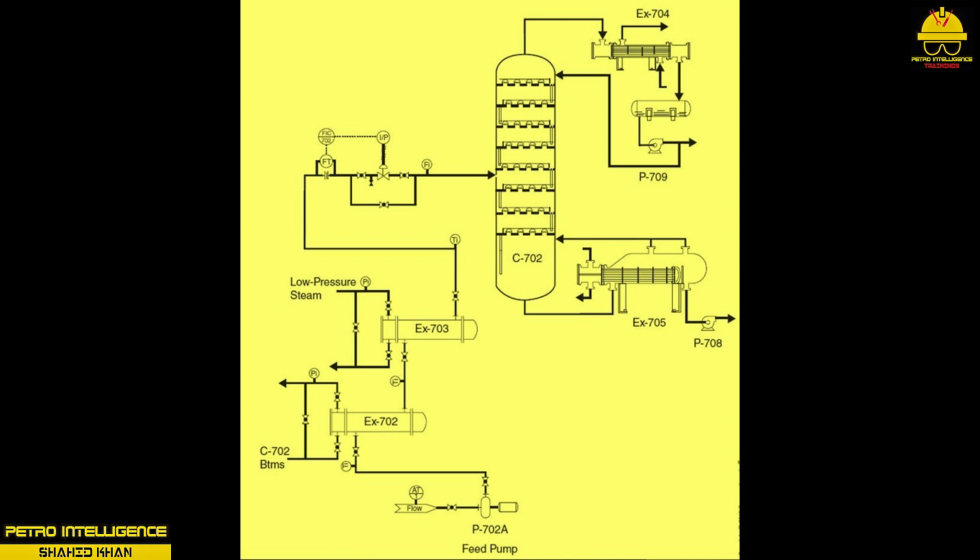As the butane-pentane mixture heats up, butane vapors begin to rise up the column. As the vapors rise and cool off, liquid begins to accumulate on each tray. As more heat is absorbed, a higher concentration of pentane vapors moves up the column with the butane, but it will primarily concentrate in the stripping section below the feed tray. Only about 2% to 5% of pentane will overlap with butane.